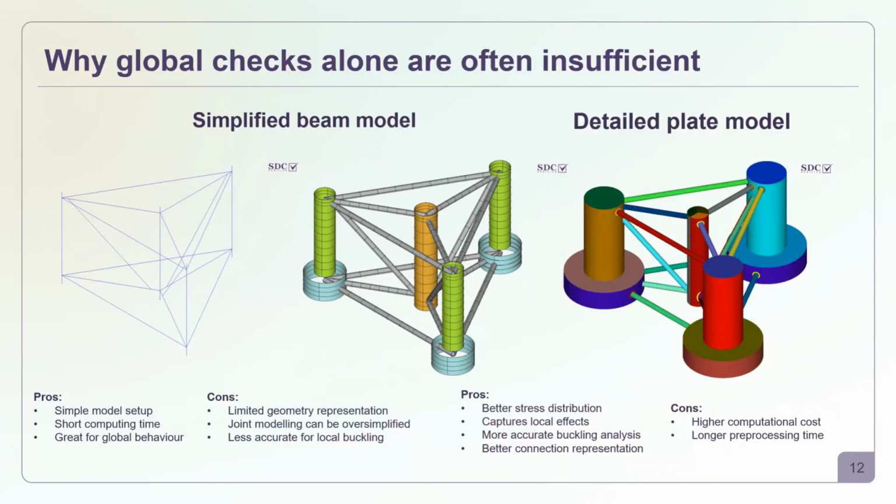In particular, as you can guess from these pictures, modeling of some detailed connections is not possible, especially in regions where you have some complex joints and connections. As a result, some local effects might be underestimated or completely neglected.